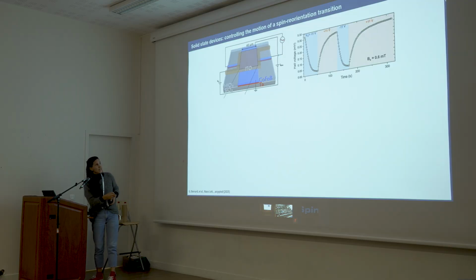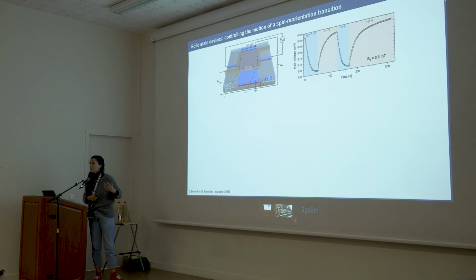So we can get here the anomalous Hall effect signal, which is the same as I showed you before, this memristive-like response with positive and negative voltages. Once again, we go from the full amplitude to the smallest, to fully quenching the signal and back and forth, because spins are following a different direction according to how many gate pulses we apply to the gate. But then we went to much bigger devices. You see this is 40 microns, so it's really big. It really behaves in the same way in terms of electrical signal.